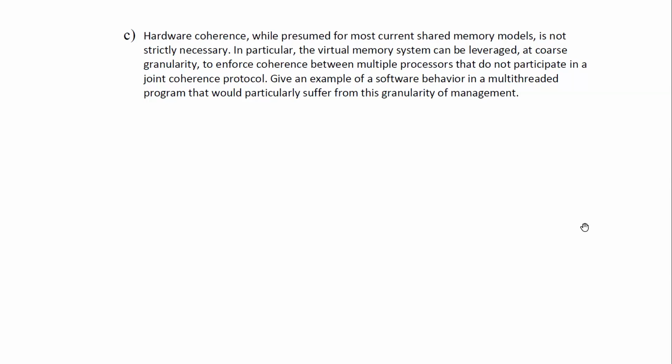The ISA may have some cache flush instructions, but your software can't go in and directly manipulate a cache-line-level granularity set of state. There's no interface for it because the cache is microarchitectural. It's not architectural. It's not defined. Right? So if I want to do my coherence in software, you might have some fundamentally incoherent hardware to start with, right? I can do this, right?